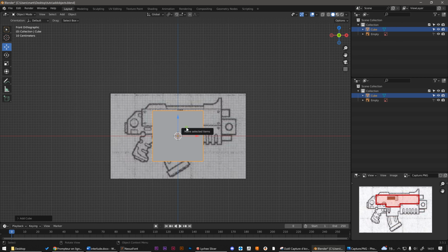So there it does not work very well, because the distance between the first and the second element was not good. So I'd better undo everything with Ctrl Z and scale the element along the x-axis to make it a bit shorter. And let's do what we did again. Shift plus D, move along the x-axis, and this time let's try to set a more realistic space between these two parts, and confirm our operation with a left click. Then I repeat this operation with Shift plus R.